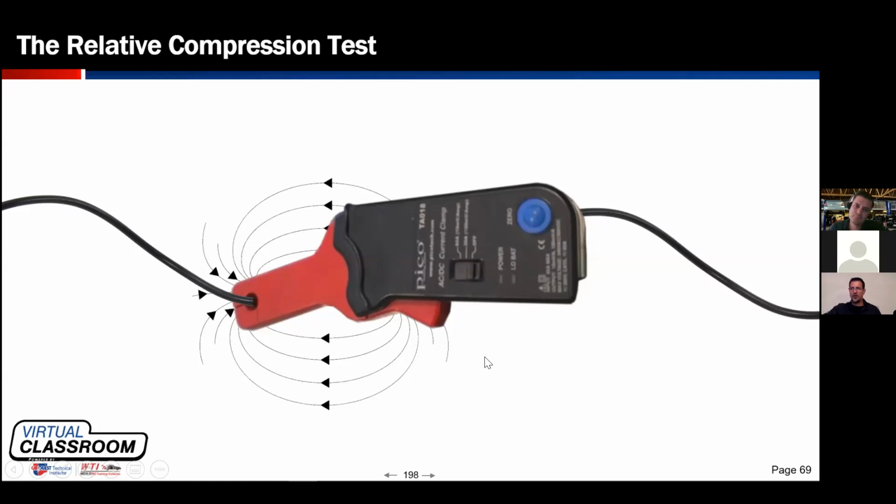There's other amp probes, larger ones that we like to put around a battery cable, and the math can be even easier. For every 1 milliamp of current flow that goes through the jaws, 1 millivolt comes out. So if we see 10 millivolts on our lab scope, how many amps does that equate to? Somebody mind typing that in chat? I'd really appreciate that.